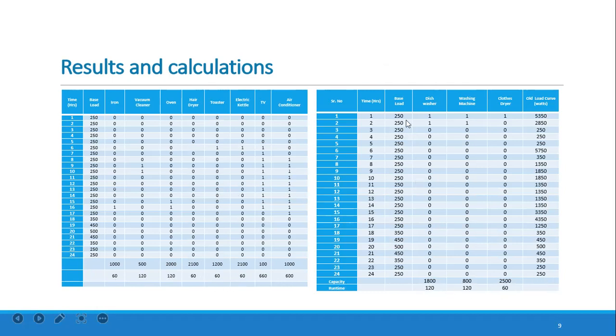The base load has been taken. What is the base load? This is the category which shows which load is on at which instant, and at every hour we have a maximum load. We will discuss it later, but to be familiar with the procedure, these are the load curve values showing how many watts of our system are being utilized at which hour. So at the first hour of the day, we are consuming 5,350 watts, which is around 5.3 kilowatts.